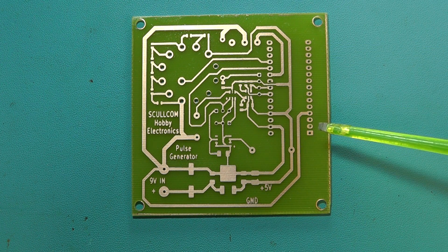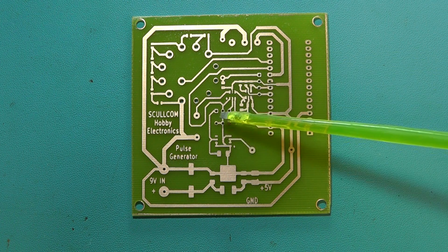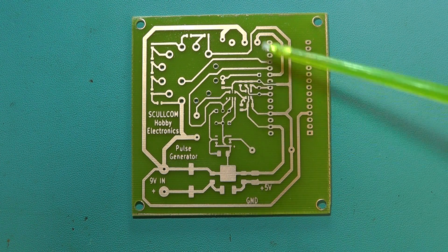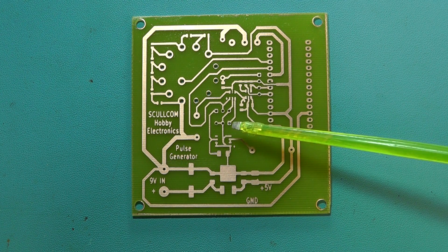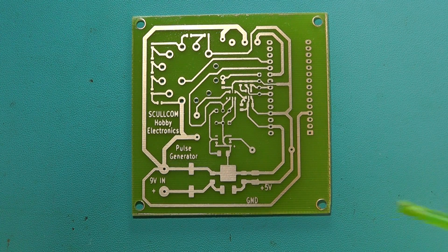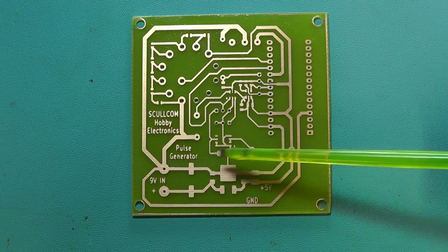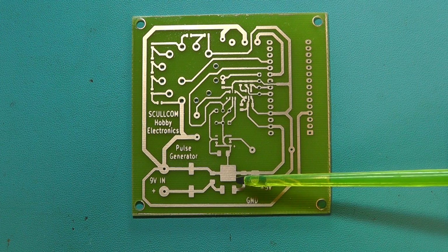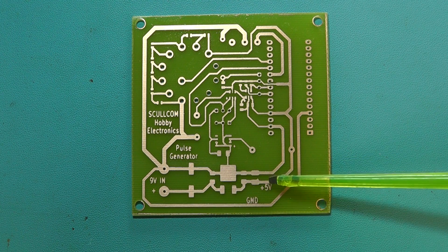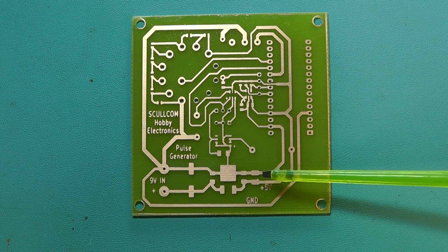which will allow us to have some extensions and updates to the project later. The other thing I decided to do is put some pin connections on for the switch and for the potentiometers used on this project, and I'll show you those as I go along. Well, I think the first thing we'll do, we'll mount the components associated with the power supply arrangement for this board. So this area here, so I'll mount the 5-volt regulator IC and its associated capacitors, and then we'll come back and test that before we mount the other surface mount components on the board.